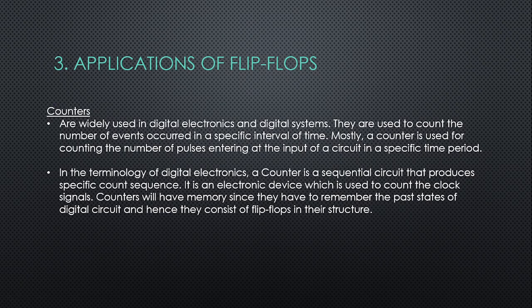Next, we have here applications of flip-flops. So first, I have here the counters, which are widely used in digital electronics and digital systems. They are used to count the number of events occurred at a specific interval of time. Mostly, a counter is used for counting the number of pulses entering at the input of a circuit in a specific time period. So, in the terminology of digital electronics, a counter is a sequential circuit that produces a specific count sequence.